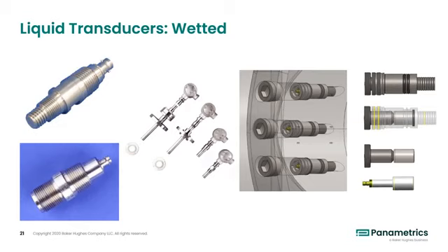The two images on your right-hand side show the way the integral transducers of the LCT4, LCT8, and the PanaFlow Z3 fit together inside the cast body flow cell. A small insert on the far right-hand side provides the pressure boundary, allowing the compact transducer behind it to be removed without requiring the line to be brought down, reducing potential downtime.